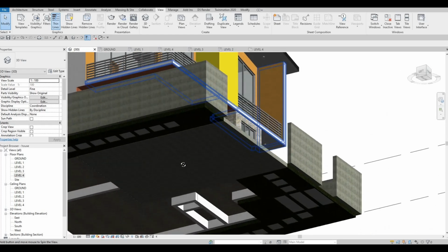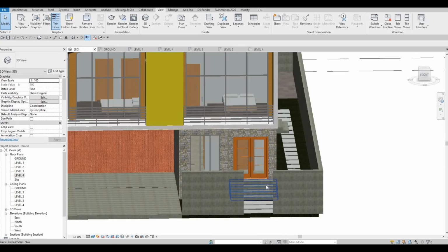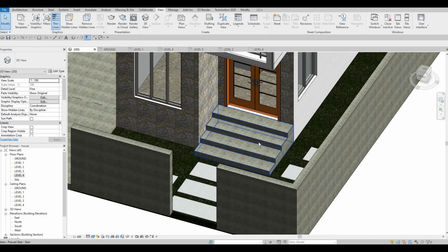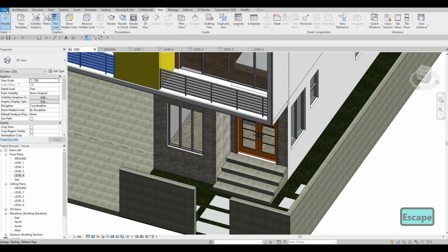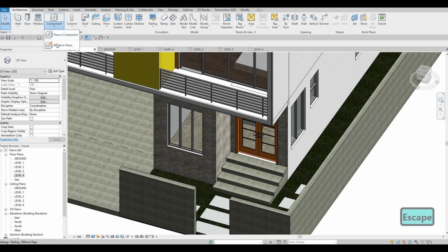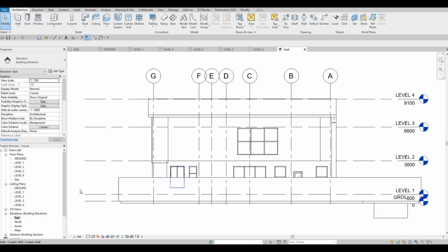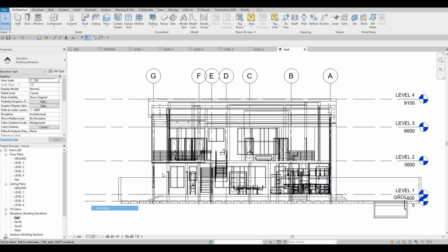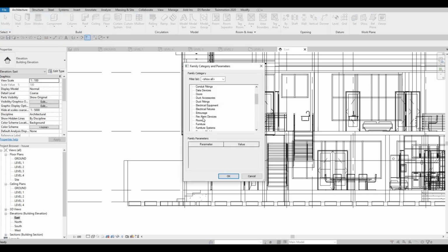And then here is good as well. I also want to change this. I'm gonna basically recreate this, but not like a stairs, but instead as a model in place. I think it's easier for us to copy this. So maybe I'm gonna do here at our east elevation and then use wireframe, and then model in place, and then select generic model,